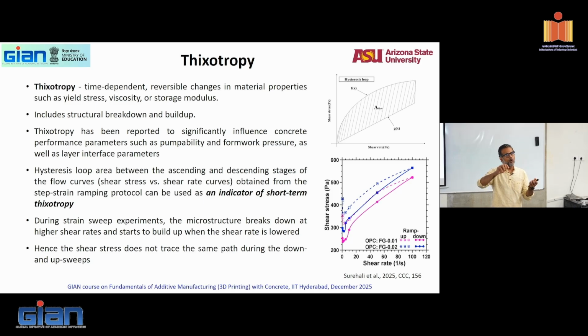See that? So slowly at 5 per second, my shear rate is slow. And then the next ramp is 10, much faster. 20, even faster. 100. By the time I get to 100, I have broken down my structure. So my up ramp is an indication of breaking down of the structure. And then I keep some rest time and I slowly come down. Right? I slowly ramp it down. Which means with time, I'm now not disturbing it that much. It means what am I doing then?